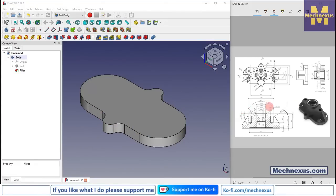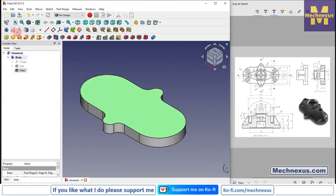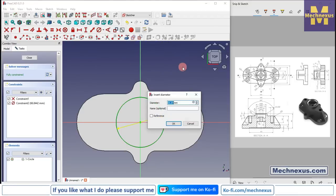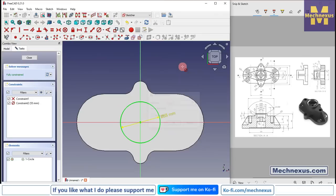And now we will create this boss here. So we will select this top face and click on the sketch, and here we will create a circle and select a diameter tool and provide it 55 mm, and we will create an arc here by projection of these 2 arc edges.